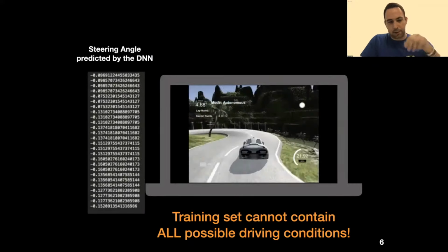Let's now have a quick overview of the experimental study and the main results. Our experimental setting consists of different tracks and weather conditions. We use the sunny condition as nominal and study the effectiveness of SelfOracle in recognizing several hundred episodes in which the car was facing an unseen condition that ultimately led to a crash or an out of bound. Thus, the main research question revolves around the effectiveness of our technique. And in brief, our results show that SelfOracle is more effective at predicting misbehaviors, by approximately a factor of 3 over the existing DeepRoad technique, when the ratio of accepted false positives is set to 5%.